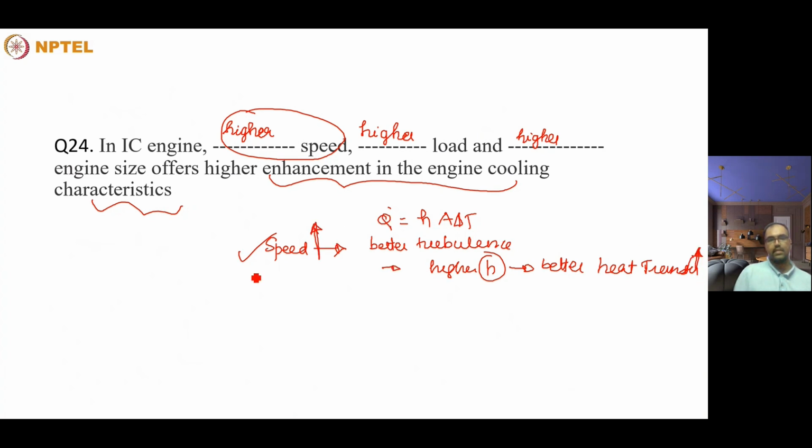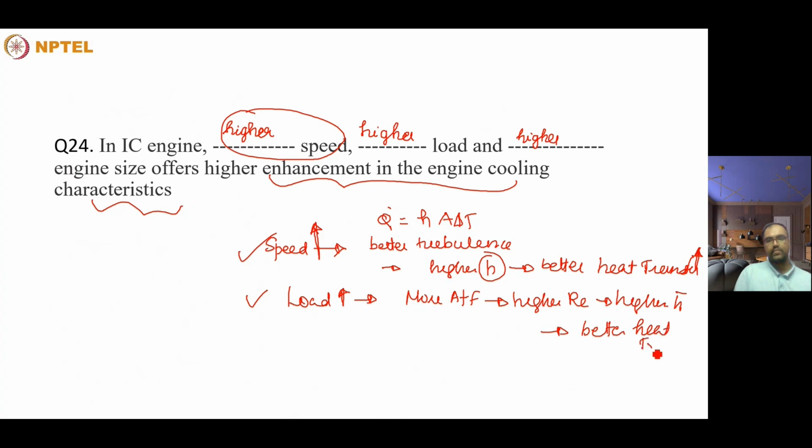And then the load increases, more air plus fuel, higher Reynolds number, higher heat transfer coefficient, and better heat transfer.